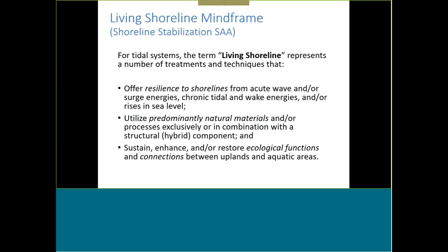And it's also good to keep in mind to be in the living shoreline mind frame. These are definitions taken again from the SAA, so that whatever you're designing, they're meeting your goals. And in the end, if you can answer yes to these questions, then you're on the right track. Is your design going to offer resilience to shorelines? That may be from wake, from storm surge, from waves, or even rising sea levels. Is it going to use predominantly natural materials, or in combination with man-made structures, but predominantly natural materials? And is it going to help sustain or enhance the ecological functions and the connection between upland and aquatic areas? So whatever you design, if you can answer these questions, you are on the right track to having a viable living shoreline.